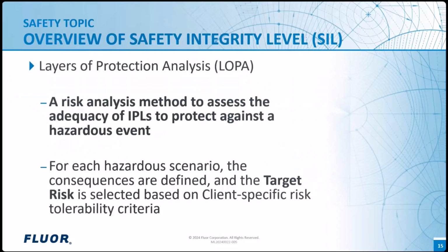LOPA is a risk analysis method to assess the adequacy of IPLs to protect against a hazardous event. It is a multidisciplinary, workshop-based methodology. For each hazardous scenario, the consequences are defined and the target risk is selected based on client-specific risk tolerability criteria.